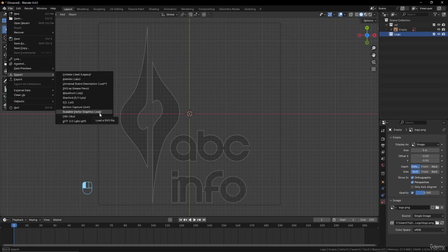You can save a file from Illustrator or maybe other vector software that makes this SVG. That's what I usually use: I go from an image, I vectorize in Illustrator and import in Blender, and you will have curves that work perfectly. Any SVG that you find online will work as well.